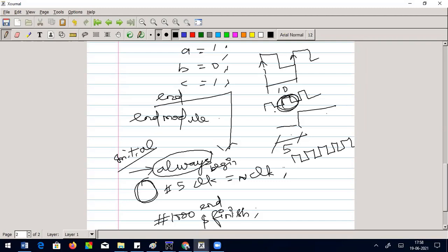So if you want to sample, this sampling frequency, this clock frequency should be less. Got it? So in that case, your time interval for changing the input should be 10. Your sampling interval should be 5. Always that sampling interval should be less than the time interval under which you are giving your input. This point is very, very, very important. Else you will not get the right answer. So make sure that you are consciously looking at this. Right.